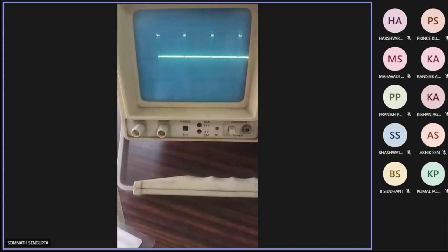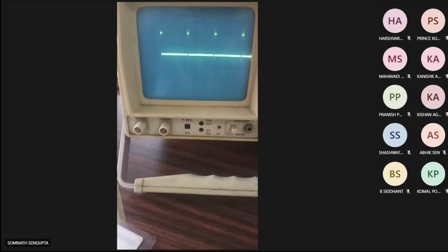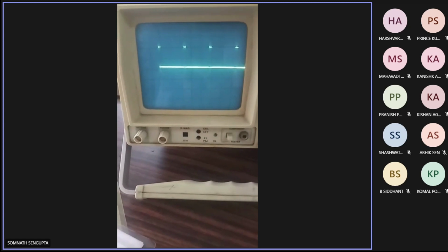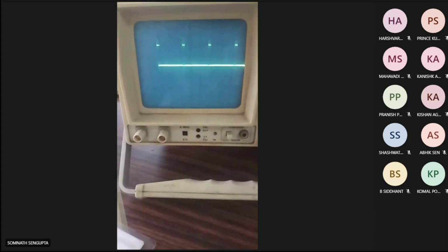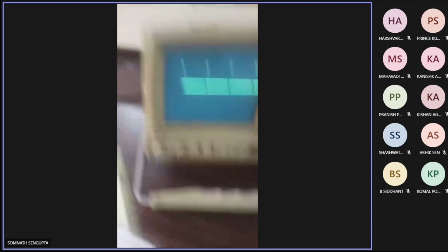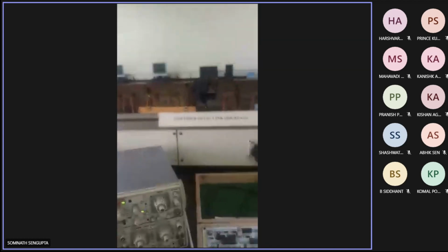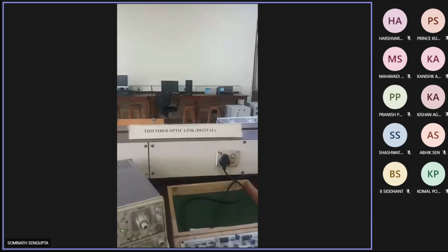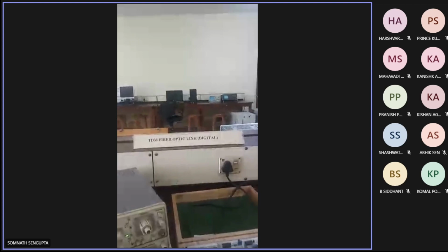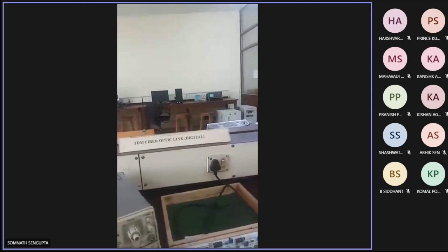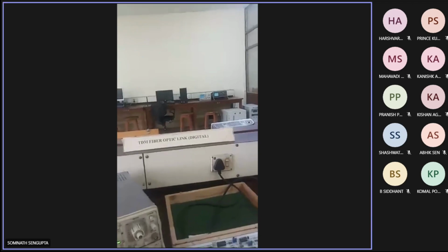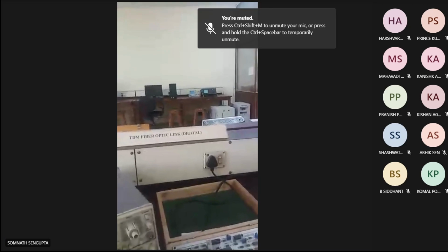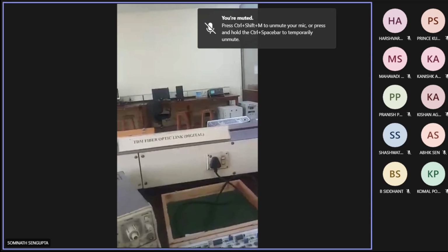That means the original frequency, or message signal frequency, should be 4 kilohertz. And that is actually the voice signal. The maximum signal frequency considered is 4 kilohertz. We talk generally in the 3 to 4 kilohertz frequency. The maximum voice frequency we consider is 4 kilohertz. Okay, so that's why the sampling frequency should be 4 into 2, 8 kilohertz.